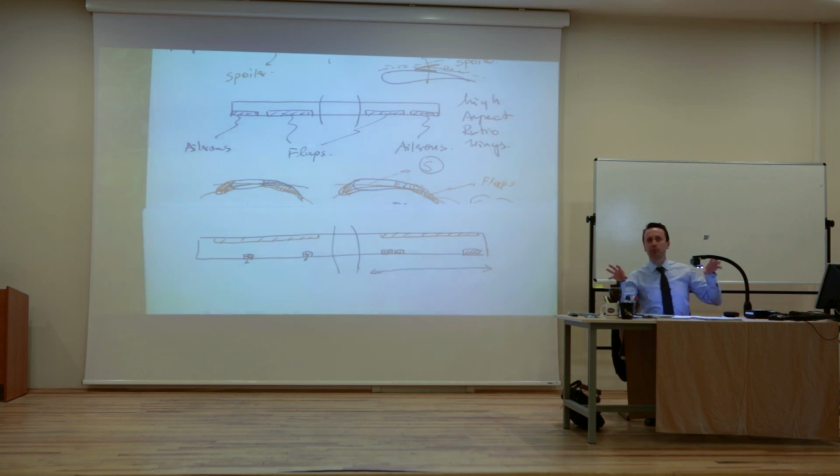All the things I explained to you, the flaps, ailerons, slots, everything, will also have an effect on CM alpha. I never really talk much about the moments, but it will change the moments. But fortunately, you have the horizontal tail that is used to adjust everything you need in terms of the pitching moment. Okay? So if there's something happening with the moment that you don't like, you always have the choice to adjust it with your horizontal tail.